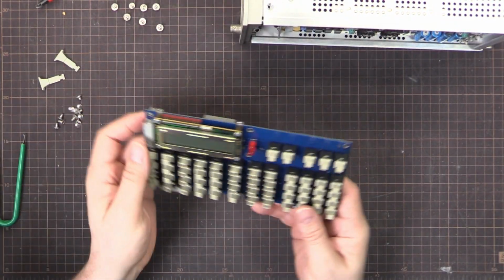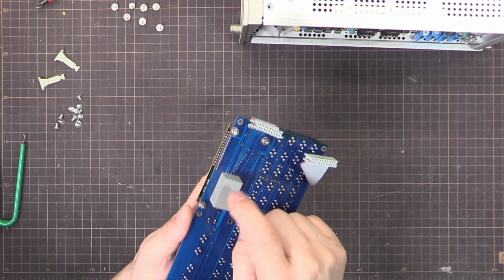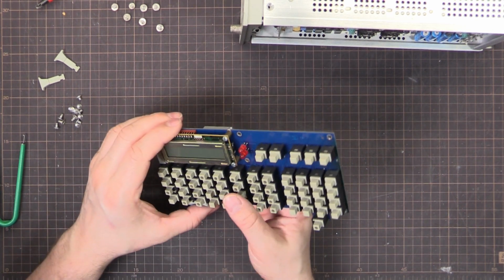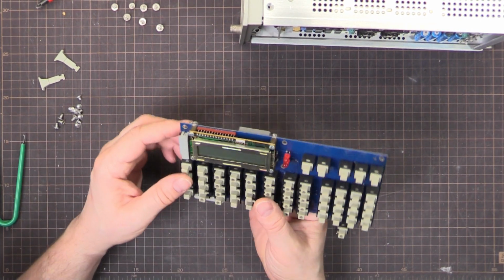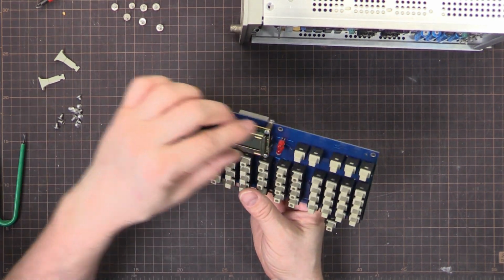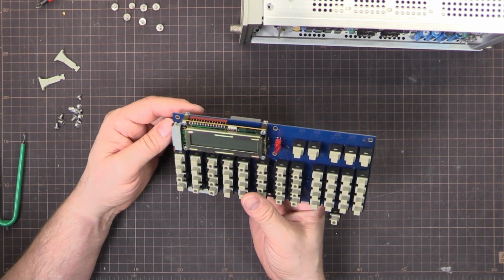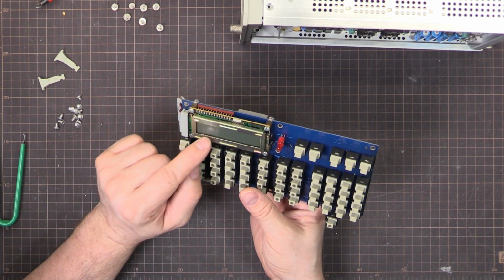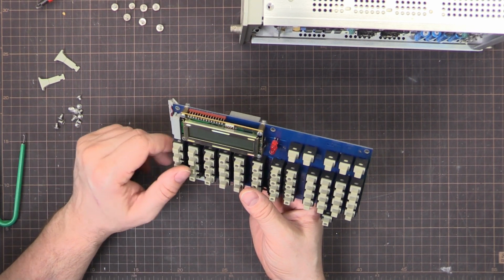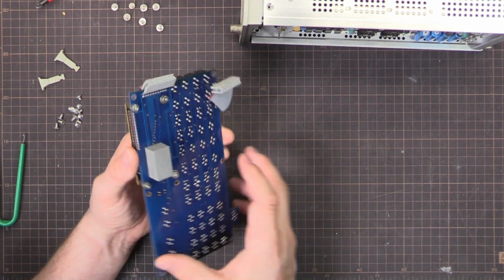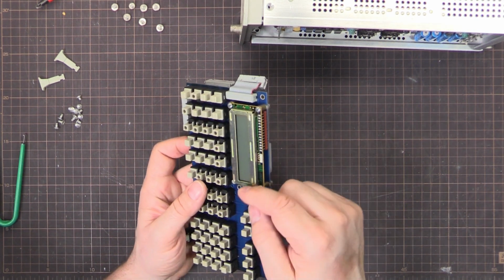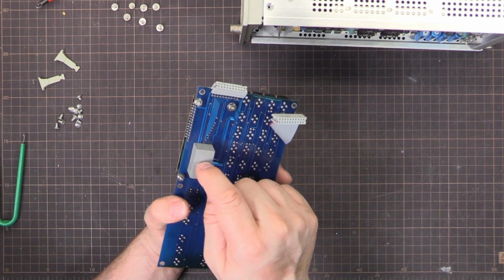And here is our front panel with our LCD, and there's the inverter for the backlight, the electroluminescent strip for the backlight. So apparently we can replace this with a standard module. That's kind of a standard sort of size there. So I'll measure that up and make sure it's going to fit something I can get off the shelf, and we can put something else in there. Now, these days we don't use electroluminescent anymore. We use LED, so I'm going to have to figure that out. It might be just a case of removing this and then connecting the LED to whatever's supplying this.